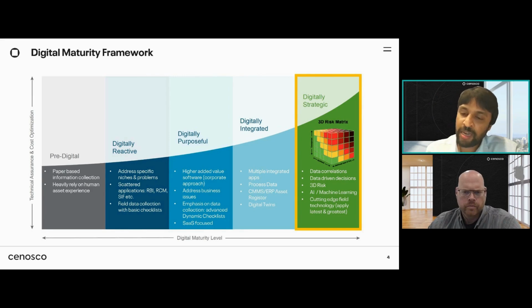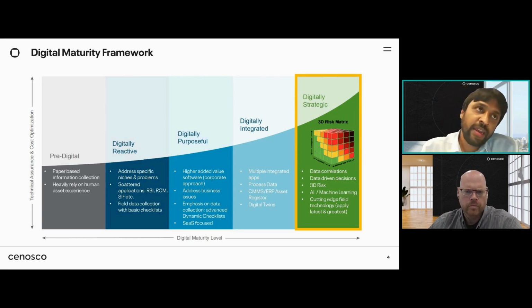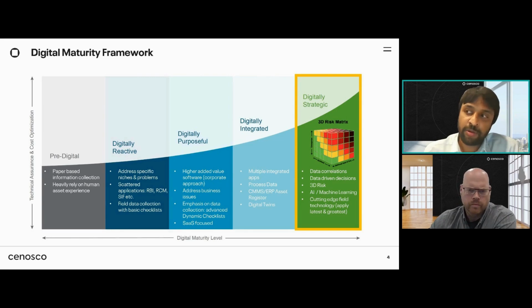So once you complete an RBI, once we know what needs to be inspected when, the outcomes of those RBIs are typically fed back, of course, to the IDMS system, but integrating to a CMMS system, create work orders, generate work orders, plan next actions would take organizations to the next level in terms of improving operational efficiencies and also feeding in data to the RBI programs, right?